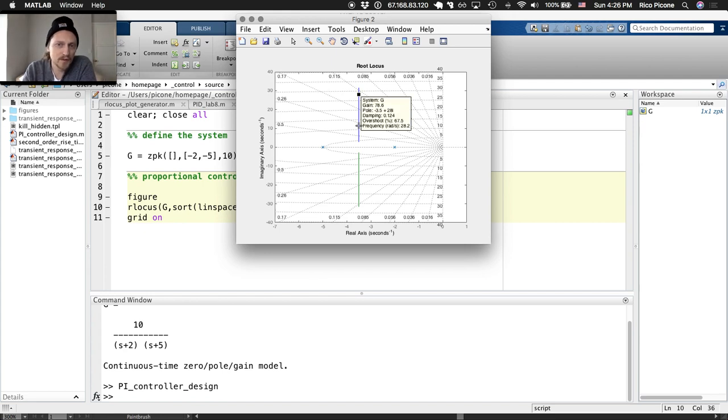Okay, so the percent overshoot is 67%, so it's higher than what we're interested in. So let's go down, lower the gain, see, we got percent overshoot of 20. Okay, we passed it. Okay, between a gain of 4.48 and 4.98. Now we could get super precise at this point. We could put in more gains in between 4.68 and 4.98 and figure out what is the exact one for 20% overshoot.